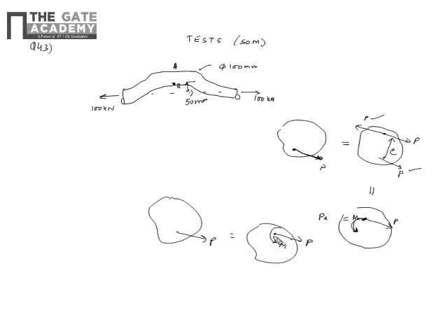Both are in force equilibrium or static equilibrium. So to understand this, I can consider this load as a load here, and the couple exerted by this 100 about this center would be 100 into the distance, so the couple will be like this, right? Or you can say the effect of this 100 at this section will be a pull and a moment, which is something like this.